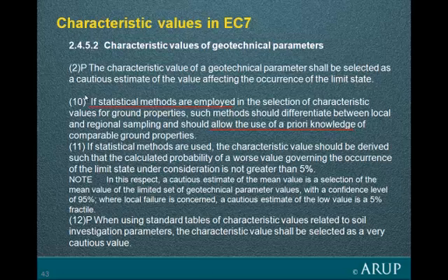So far I haven't mentioned statistical methods at all, and Eurocode 7 says that you might find statistical methods useful, but be very careful with them. If they're used, make sure that you're not throwing away any knowledge. You're not throwing away a priori knowledge of what happened on the next door site or what you can read about this stratum simply because you've got a few test results and you can do some statistics. That would be a dangerous path to go down.